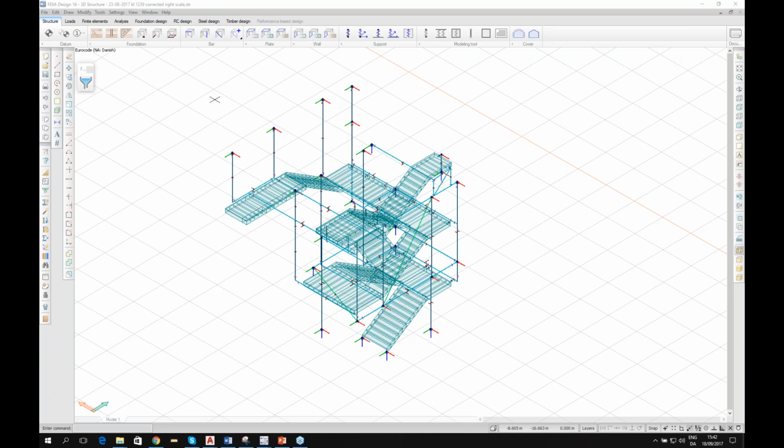Mara, when you connect the different members, I normally always use this line-line connection and point-point connection, because then it's easier to see what forces go through the connection. If you model something to intersect, it's more difficult to see what forces actually go through it. Of course, if you have a normal building with slabs and walls, you don't do it like this. You do just edge connections, and you change one of the values away from the rigid, and you see your edge connection results. So an edge connection result works the same way. It's just a finite element member in between the plate and the wall.